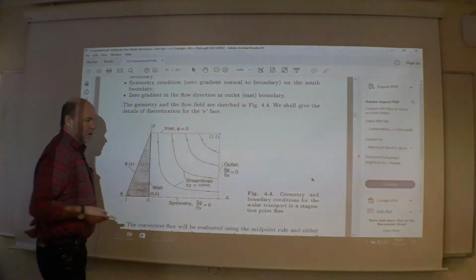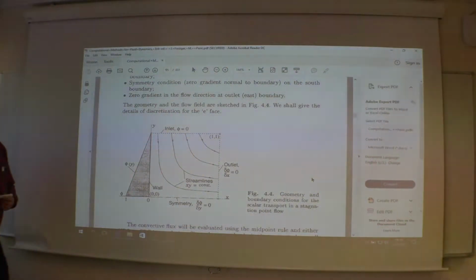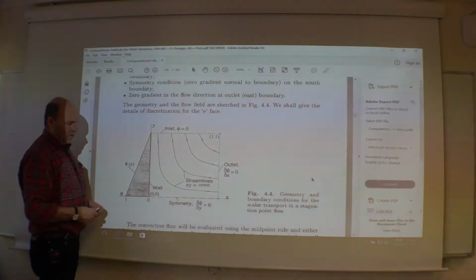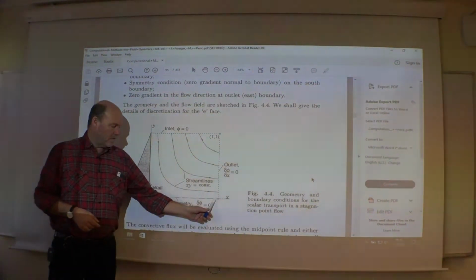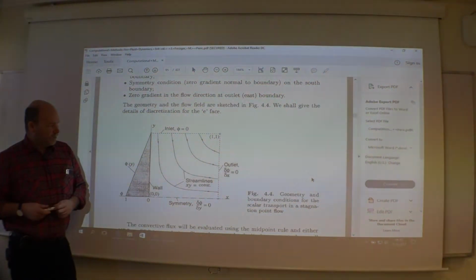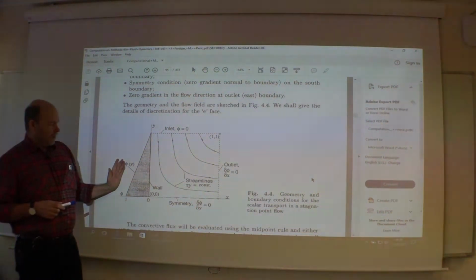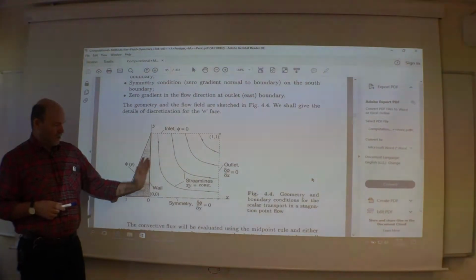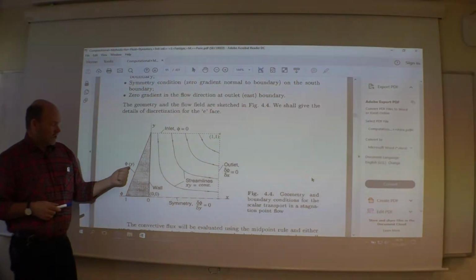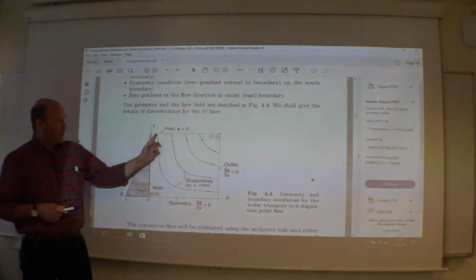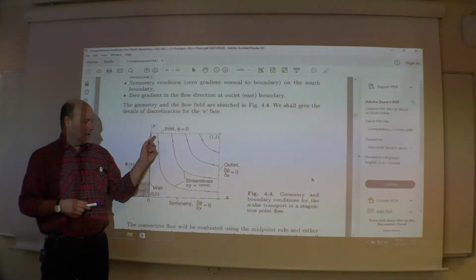And then we only look at the first quadrant and say the y-axis is a solid wall. Down here we have a symmetry line. And then we have a possible flux, a diffusion of this quantity phi into the stream through the wall here. We send in just 0.